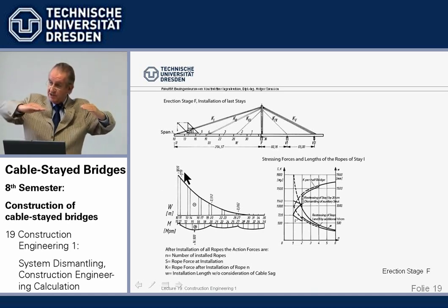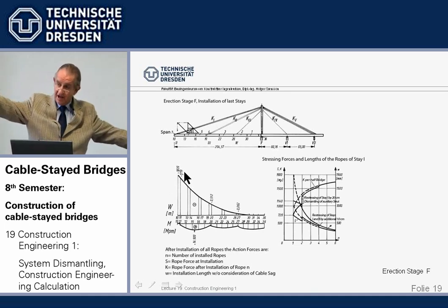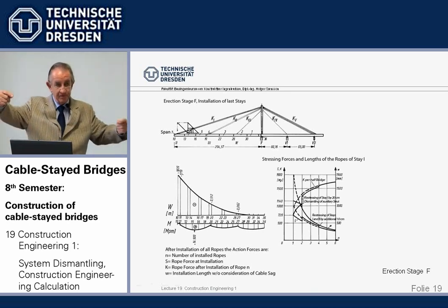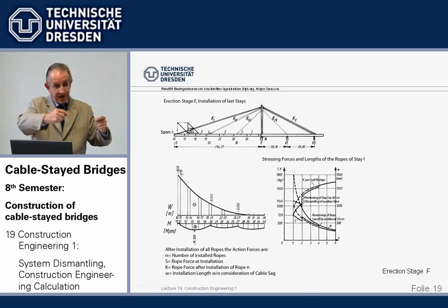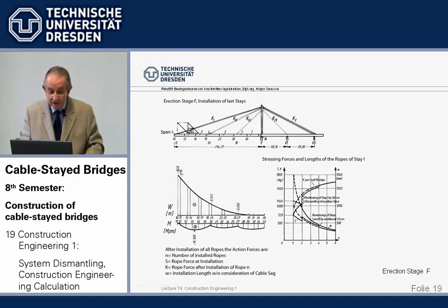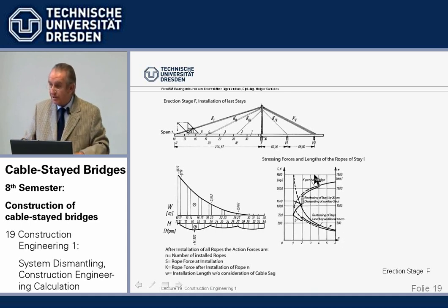And you can imagine the cable is inclined, what length, so to say, with a tie rod, you have to stress the cable to get 3.6 meter beam movement up and down. But it's all there, and it shows you for the intermediate stages that you can check the cable force and the tip movement in accordance to the cable installation.